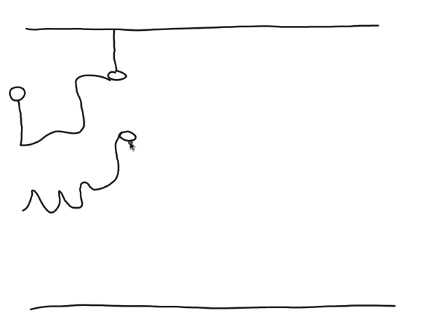Now, we'll put a resistor in here. So that bit's a bit different from before. And we're going to use this as a potential divider. So at the moment, this is a big resistance. It's massive. There's no way the current can flow between this. So you're going to have a large voltage drop across here, and this point would more or less be at 0.